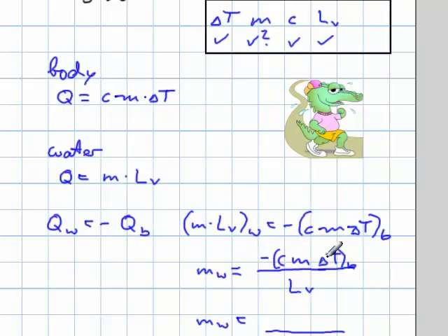And then with this negative and the negative that I introduced over here, that of course becomes a positive numerator. And then divide that by the 2,420,000 joules per kilogram, the latent heat, and so that one also comes out to a positive number for the mass. And when you look at the units, you come up with a nice kilograms for that one. And that's how much mass would be evaporated. It's going to be in the neighborhood of almost half a pound.